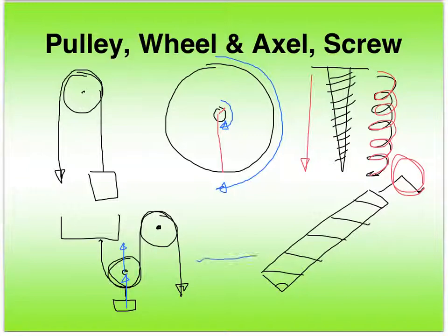So let's say I have water up here. It'll allow water in. And as I turn this, it creates a gap right here that collects water. And as it turns upwards, this screw that is fit snugly inside that tube doesn't allow the water back down. And there's a hole at the top, and that water will actually spill out at the top. You can go on YouTube and look up Archimedes screw and see this actually work.